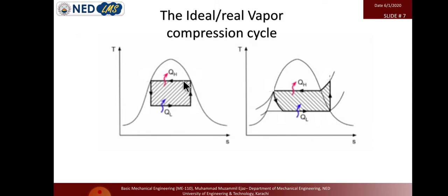The condenser changes the phase from gas to liquid and releases heat at the outdoor. And in the expansion valve, we have a lower diameter and suddenly a larger diameter. So due to the decrease of pressure, it gets cooled down. And in the evaporator, the liquid refrigerant again takes heat and the phase change process occurs.